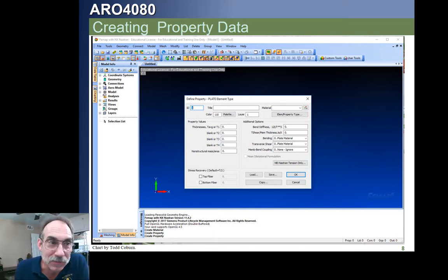Most people that think they're expert users and are regarded as expert users actually aren't. They're maybe good at pushing buttons, but they don't really understand all the details of what they're doing. You should not be putting material properties in these boxes unless you have thoroughly tested and know exactly what it's doing. So for most of the time, our membrane elements like this will just be having membrane stiffness.